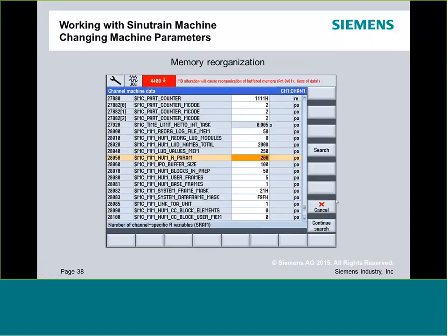Now, with the nature of changing parameters, be careful. Be careful when you get to parameters that cause a memory reorder. If you get to a parameter that's going to reorder memory, you're immediately going to see this alarm: this MD alteration would cause reorganization of the buffer memory. You're in trouble now. Generally on a machine tool, when this occurs, you make an archive, you reread in the archive, it reorders the system memory, reallocates memory from different areas. Everything's good. Sinutrain does not have an archive mechanism.